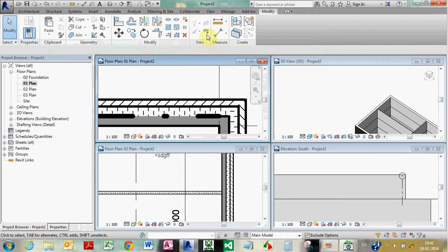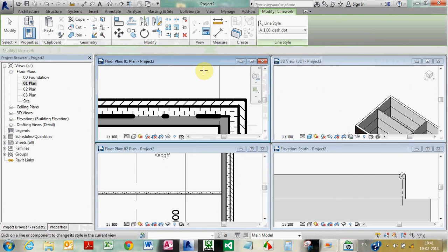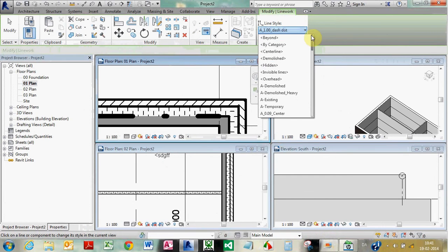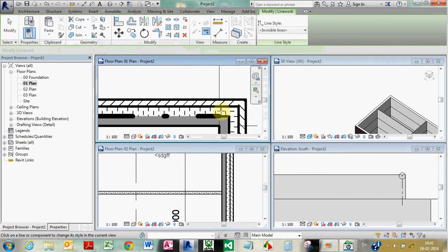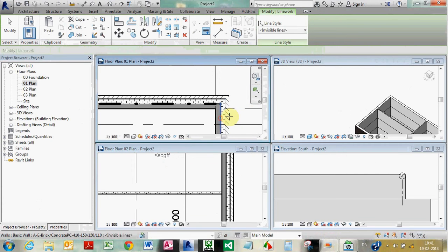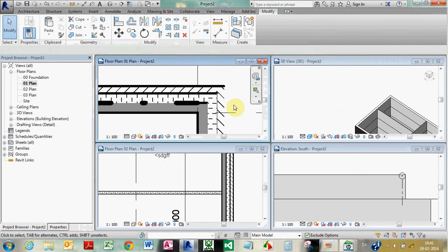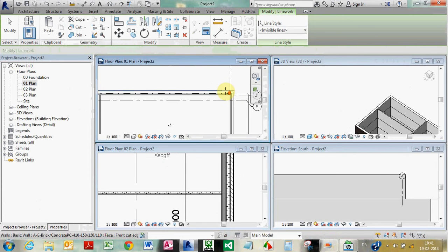The one most used, instead of hidden stuff, maybe it's a part of a 3D object you want to hide, but if you use this hidden view, the whole object will disappear. Then you have this option, line work, and you can use this line type called invisible line, and then you can hide single lines in the views. It doesn't affect anything but this line in this view. You can even hide a part of a line.